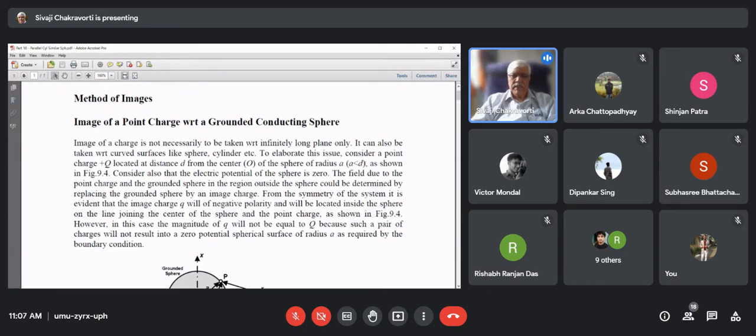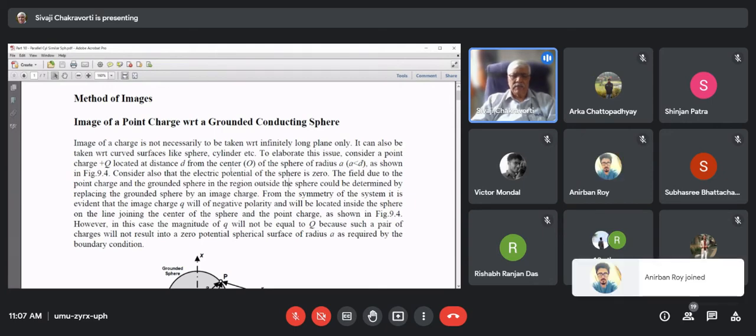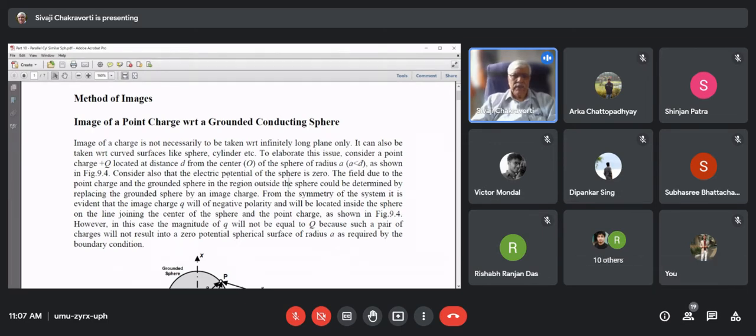Now, sphere gap arrangement, I am not sure whether you have seen it in the lab because of this pandemic and all that. It's two metallic hollow spheres, and they are arranged either vertically or horizontally. There is a certain gap distance between the two spheres, and of course, it's natural atmospheric air between them.